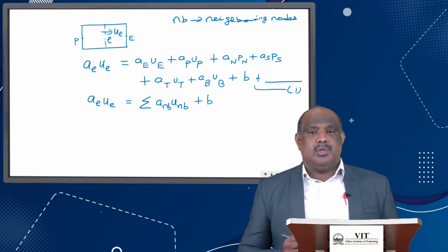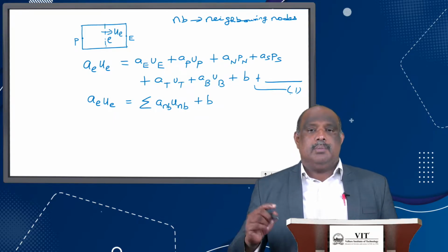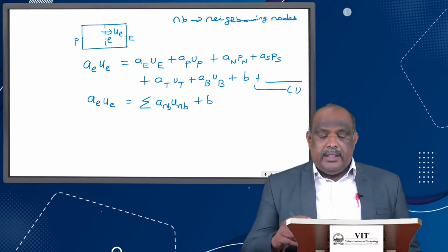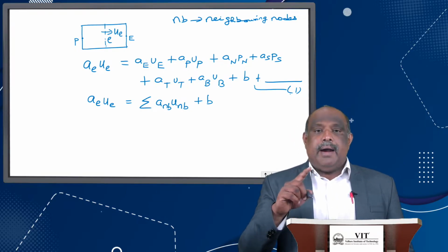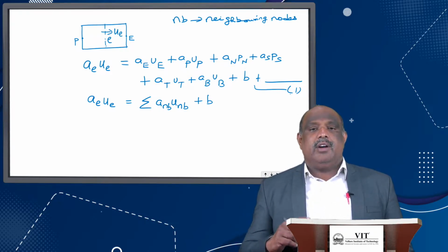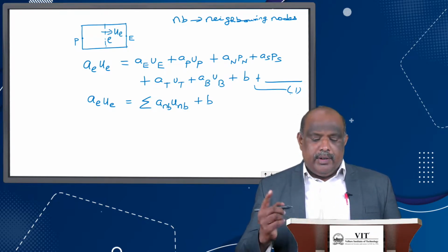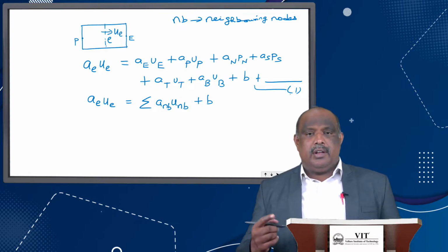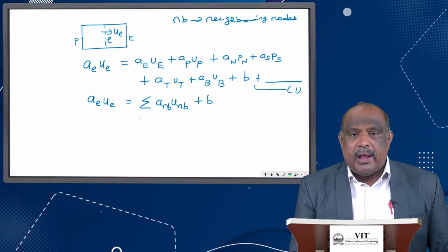This B is nothing but the source term. Along with this, in the u momentum equation we have the term minus dou P by dou x. Yesterday itself we derived the value of minus dou P by dou x. Even if it's not wrong, we will derive it once again so that we will have more familiarity, but I will make it fast.